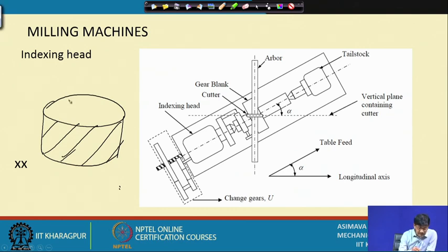But if you take a section, you might find 2 or even 3 teeth taking part in the transmission of power in case of helical gears, and also their operation is much more silent and they are less prone to shock loading, etc. A number of advantages are there, because of which machining of helical gears is one of the most commonly carried out practices in machining.